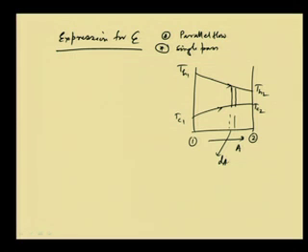So, if I say the differential heat exchange dq dot, that will be equal to minus m dot h into Cph into dTh, because this heat is being released by the hot fluid, and dTh is the final minus initial, so that is a negative quantity. Therefore, we have taken a minus sign, and that is equal to m dot c into Cpc into dTc.